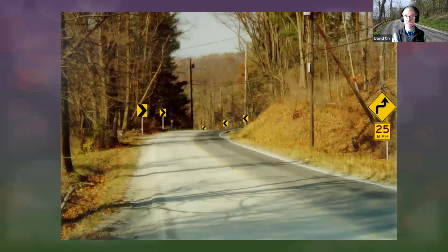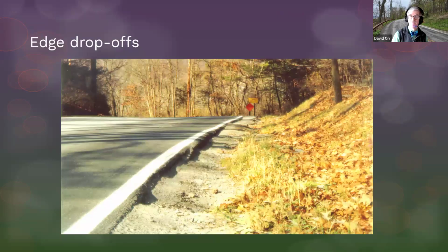So when we looked at this particular site, the minimum would be to put up the proper signs and the proper delineation. That's the minimum starting point. Some of you caught it, but again, when you walk a site and you start looking at it carefully, you'll see things like an edge drop off where people were cutting the corner and they were going to have problems.